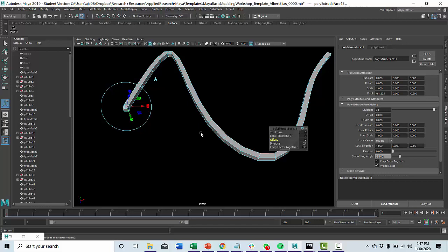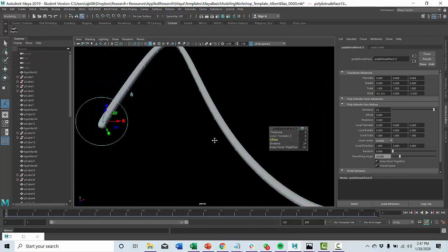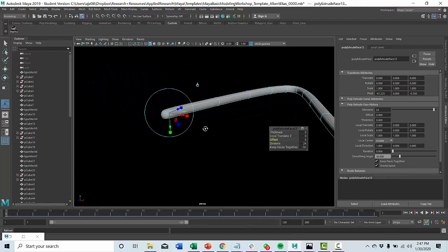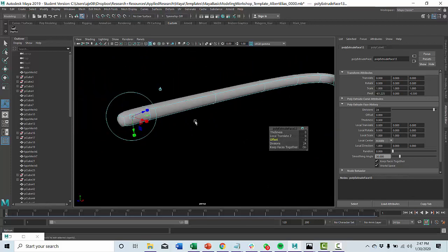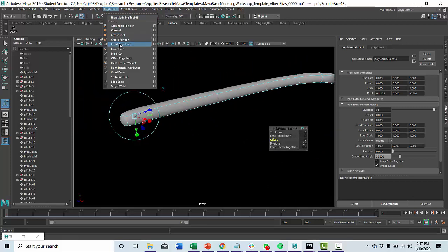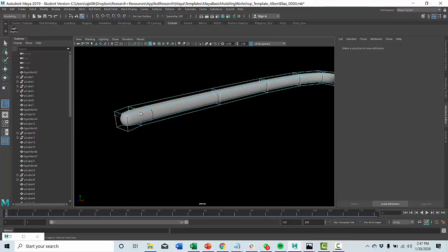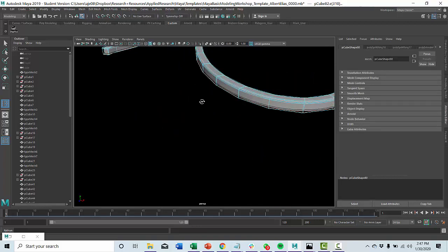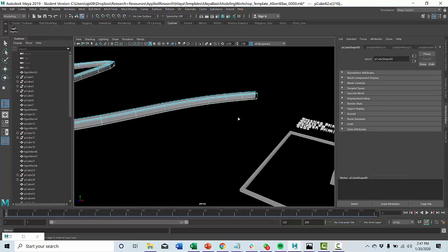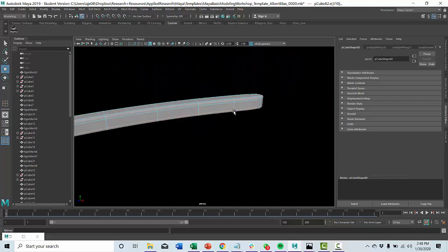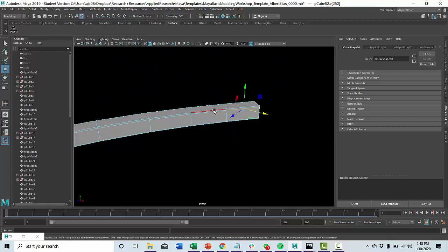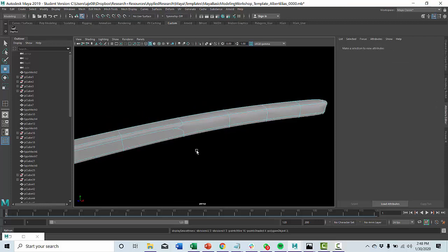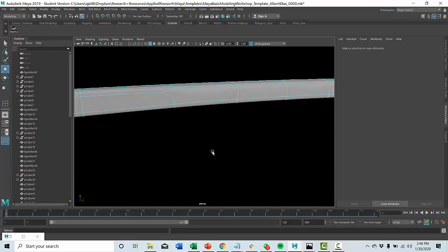Yeah, so if you wanted to do that, so if we were in Maya right now, you would just have to control where you put the edges. So in that case, you wouldn't maybe use an edge loop, because if you add an edge loop, it's going to make the whole thing, right? So if you wanted the other end to be smoother, what you'd have to do is go in and delete these loops at the end, which then you'll start to get a little bit of strange geometry, but you'll get that rounding back that you didn't have before.